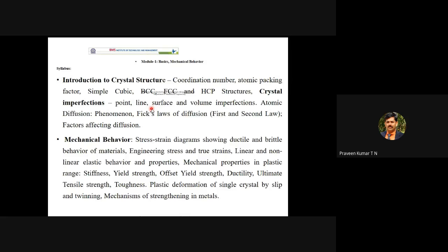Most students, if they say in metals, in solid, in workpiece, in sample piece, that is the type of answer most students write in the examination, even for the test. No, you cannot write like this. If one atom is missing, or a carbon atom is missing, or any one atom is missing from the unit cell or crystal structure, then it is referred to as a point defect. If a line of atoms is missing, then it is referred to as a line defect. On the surface means not on the... imagine you have one metal rod.